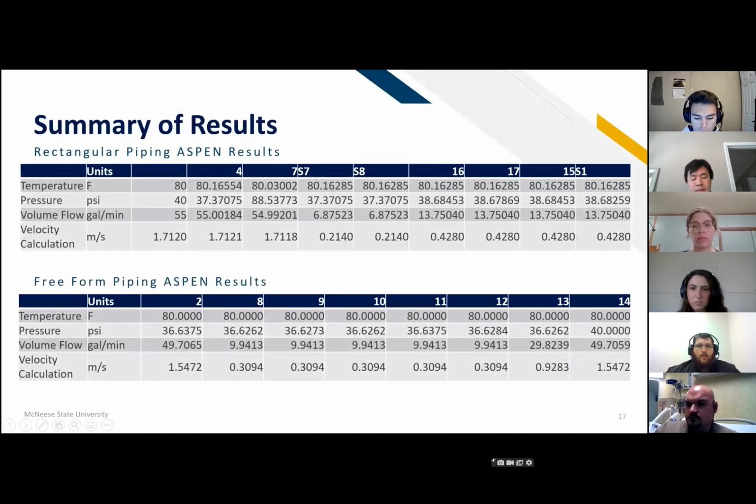In order to find the overall flow rates in the piping system, the flow rates for these pools branch off and form a parallel piping system. And these individual injection points into the pools have to be added together to determine the overall flow rate throughout.